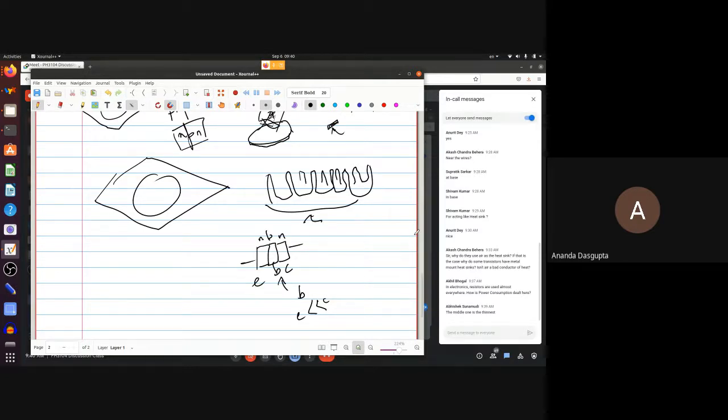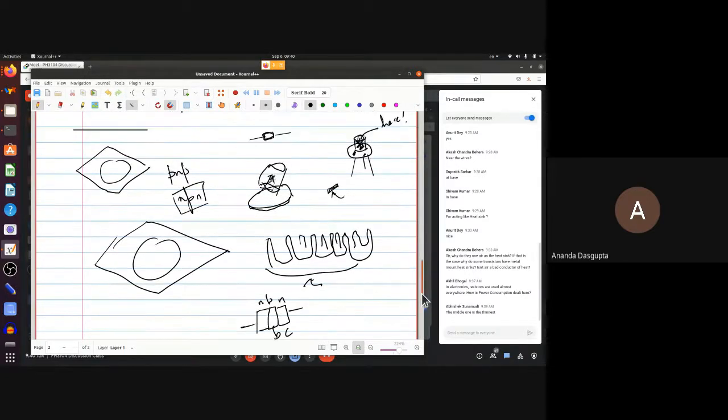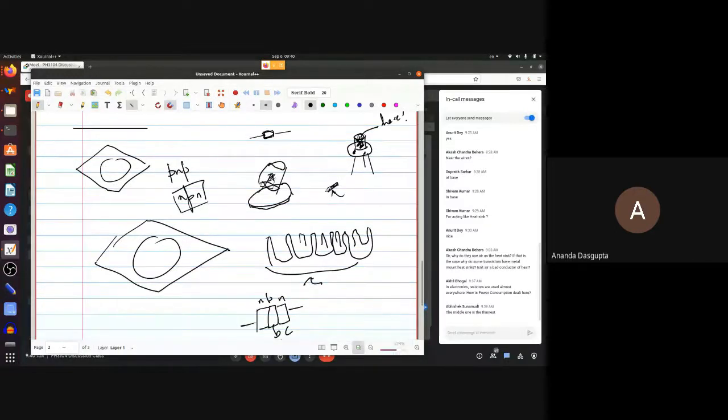And also, I did say that there is a semiconductor piece in the middle of the plates, but it's the collector which is in touch with this plate. So the collector actually is in thermal contact with the plate, and the plate takes away the heat from the collector. Okay. Fine. So these are very important issues in actual construction, and they all have their reasons. They're not just there because somebody suddenly thought, let's make the base thinner. Okay.